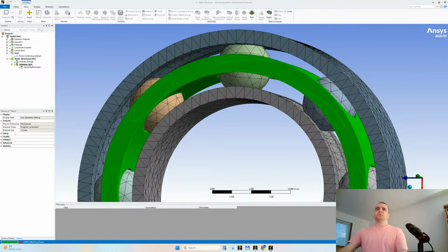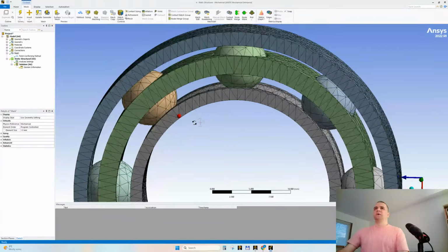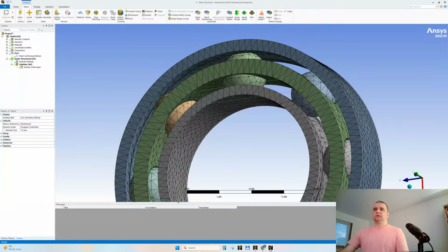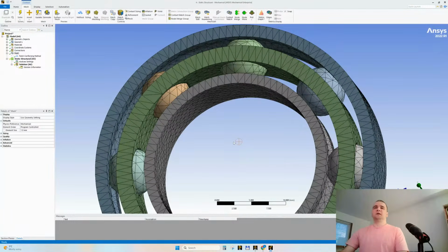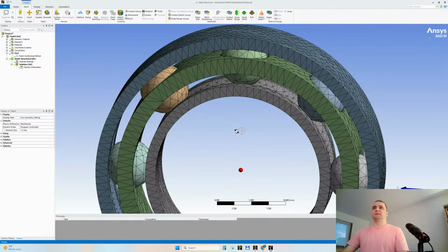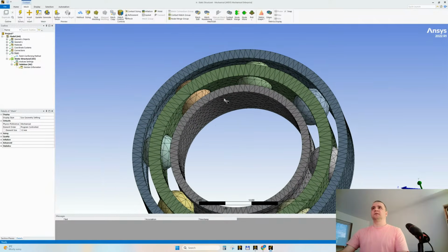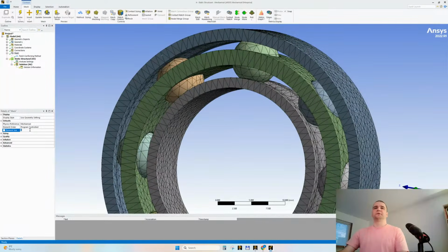You'll maybe ask, hey, Claude, why do you make them so coarse and about Hertzian contact? At this moment, we only need to have very fast, quick iterations. This means we need to have a coarse mesh. After we have obtained a very nicely moving and rotating bearing, then you can choose to refine the mesh and make it more decent looking. But at this moment, let's make quick iterations, and we'll be satisfied if everything rotates according to what we need.